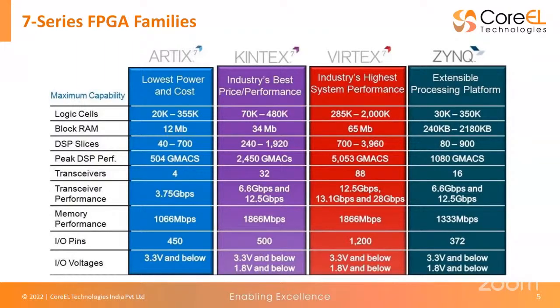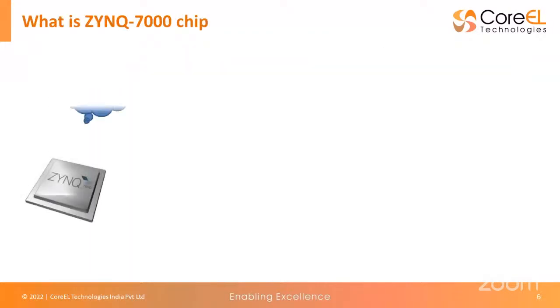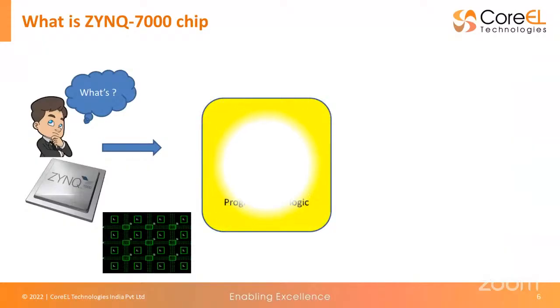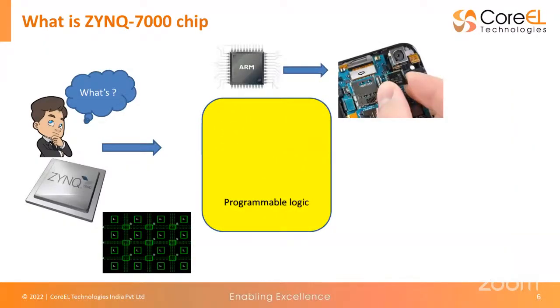So an extension to the pure FPGA architecture is going to be our SoC based designing. SoC based designing is when we have programmable logic, which is the PL, the pure FPGA logic blocks, embedded within an ARM-based chip. For AMD Xilinx chips, we're mostly talking about ARM-based chips, right? So you have a processing system which is ARM-based, embedded along with your logic resources.